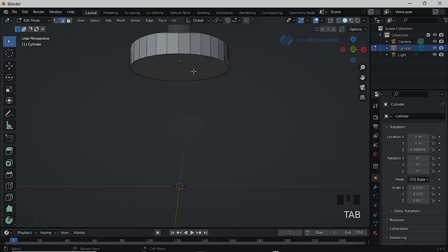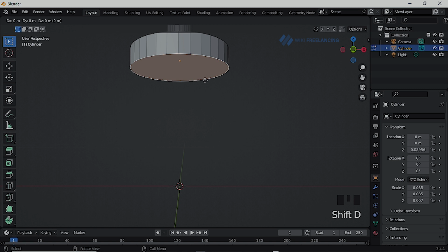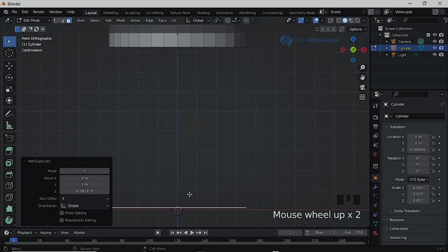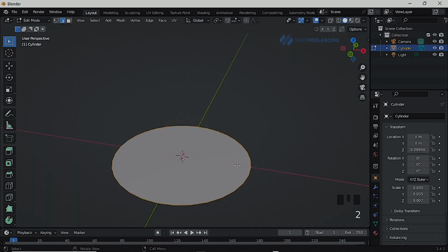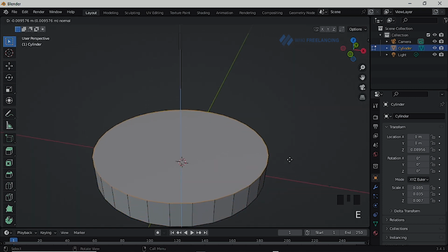I have to select this face, hit 3 so switch over to this panel here. So this is 1, 2, 3, right? And you can easily hit Tab to switch over from edit mode to object mode. Shift D to copy it and take it down here. So hit 1 and set it to 2 for the edges, and then extrude this in Z direction.